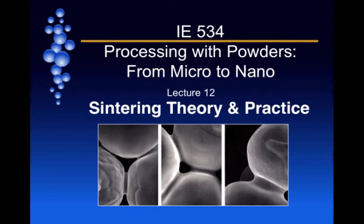In today's lecture, we will deal with sintering powders. So you created a shape and now you want to develop bonds between the particles and densify them. And so here you can see, for instance, the formation of this region called the neck, based on atomic transport from this particle surface to this particle surface.